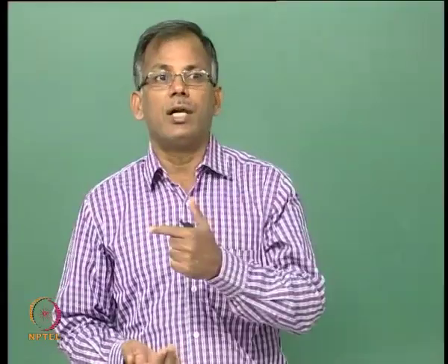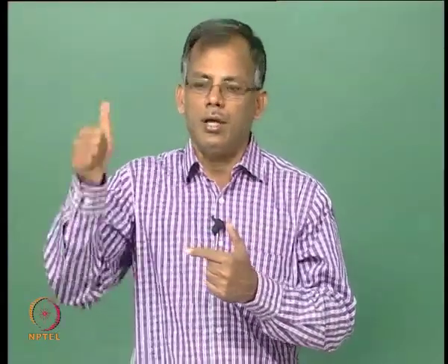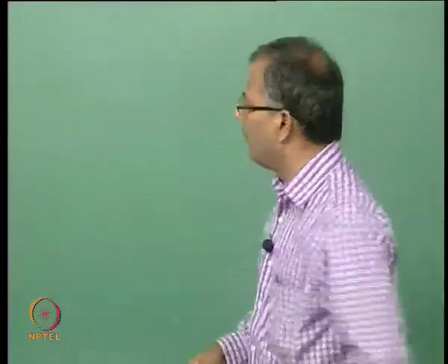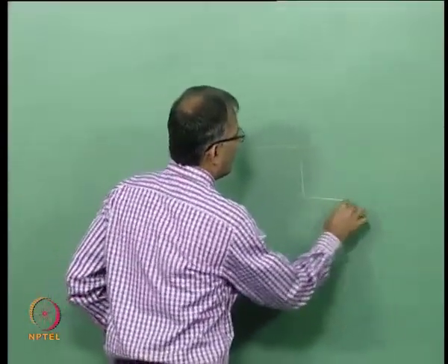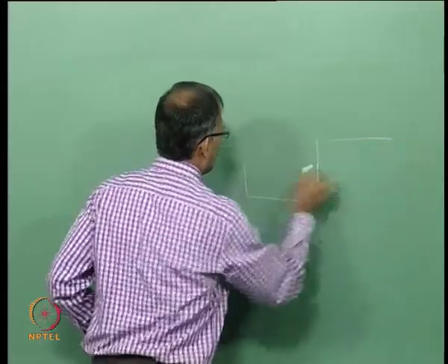See, for example, when I apply foundation pressure, below the foundation the soil is getting vertical stress and getting horizontal stress due to this, and then on the side of the foundation the primary stress is horizontal, trying to squeeze the soil upwards. If we draw one picture, for example, so you take a cut foundation, something like this.